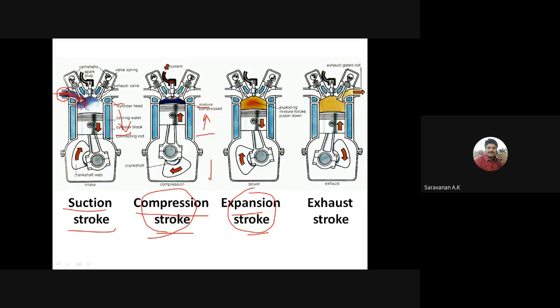When the piston is near the TDC, the spark will be ignited, right? So once the spark is ignited, the high pressure and temperature air fuel mixture is burned. Due to this burn, the chemical composition is burned, and the pressure as well as the temperature drastically increase.